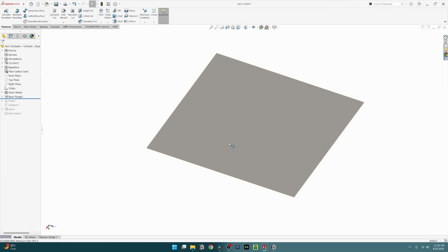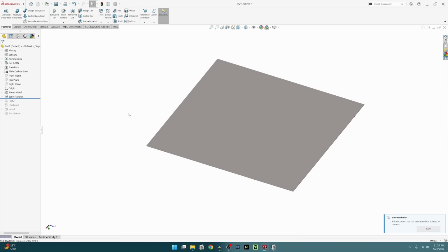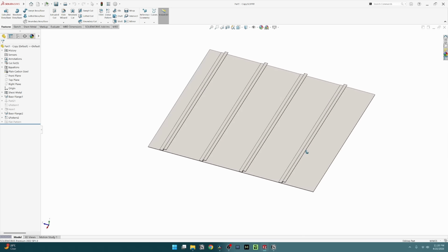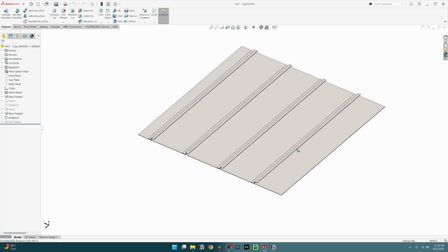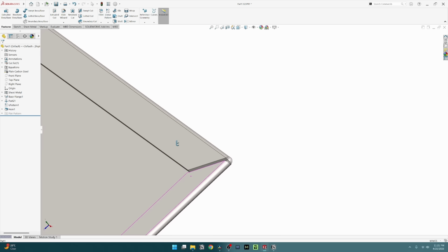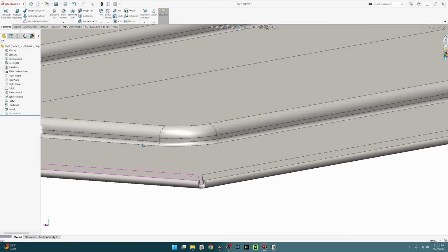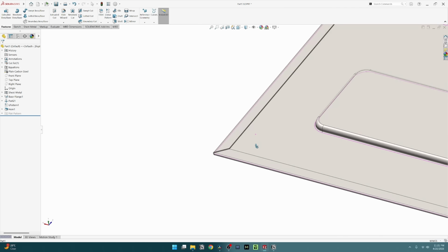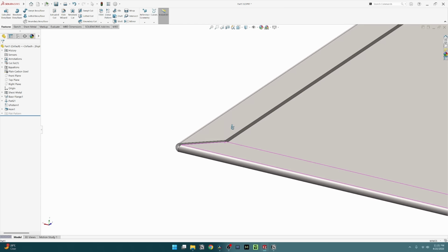Now let's also take some sheet metal examples. If you're designing a flat sheet, it can buckle. So instead, you can add some curvature or waviness, or weld some ribs. You will find this design technique in standard products. And to strengthen the edges, use hemming. It also removes sharp edge problems. So the idea of design for strength is to achieve the maximum strength with minimum material and weight.